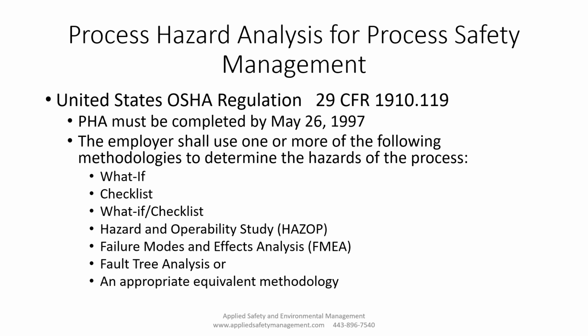So what I like to do is to do the what if approach, and I just say what if, and then I have the valve, the motor, the process vessel, the piping, whatever it's going to be, and just say, what are the scenarios? Am I going to have a leak? Am I going to have a breach? Am I going to have something that's going to cause a buildup inside of my pipeline? And thus, I have to break the pipeline every so often to clean out the buildup to then reinstall the pipeline again. And just look at what your scenarios are that you have out there then.